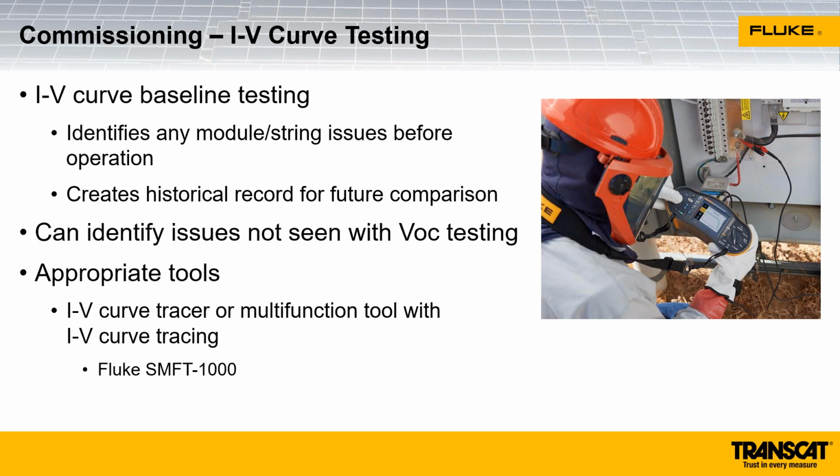And you can see on the picture here, that's the IV curve right there. That green curve there is actually the plus or minus 5% of what we expect. So you can very easily see if the IV curve trace passes the test when you're using that tool.